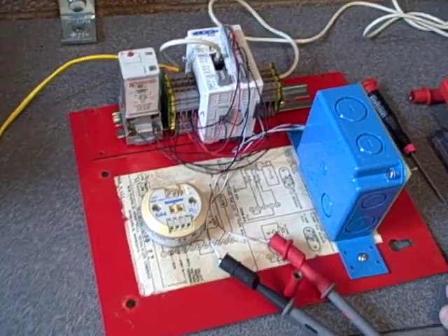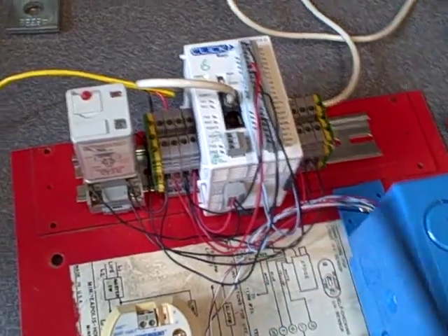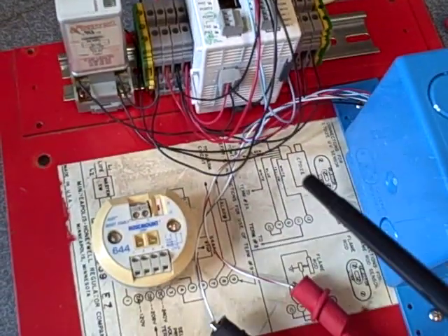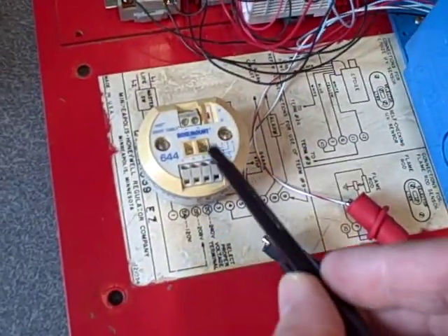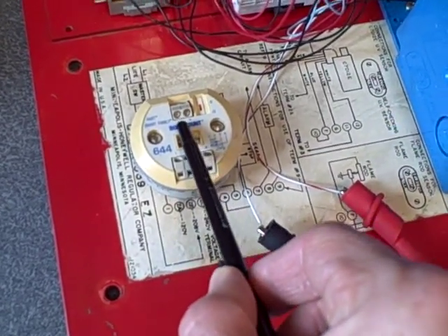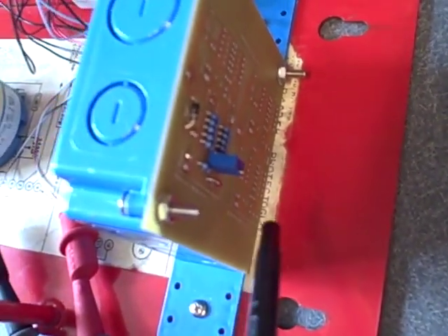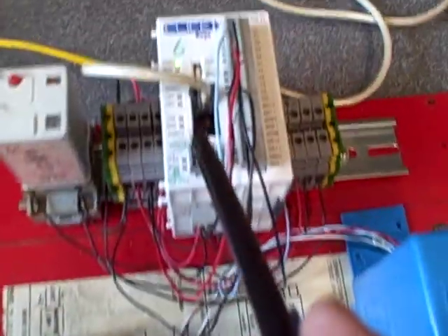In this project, we're taking an Automation Direct CLICK Analog PLC, 2 analog input channels. We're using one of those channels to monitor the temperature of a thermocouple. This is a temperature transmitter taking the thermocouple signal and outputting 4 to 20 milliamps. That milliamp signal comes over to this circuit board here, which takes that 4 to 20 milliamp signal and turns it into a 0.6 to 3 volt drop, which is then measured by the PLC.